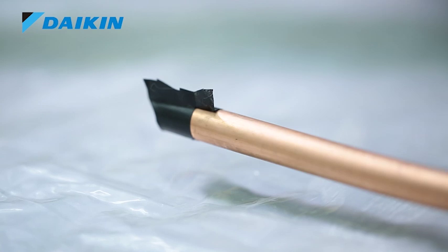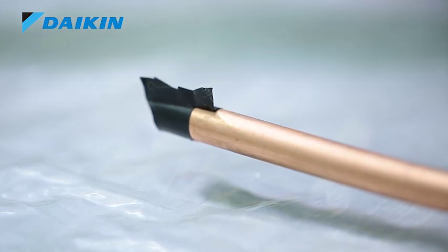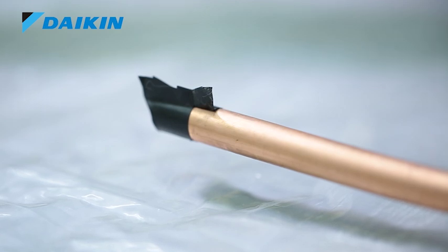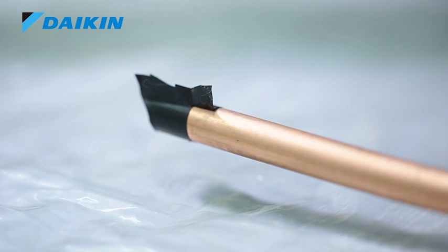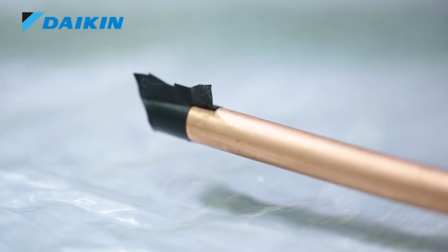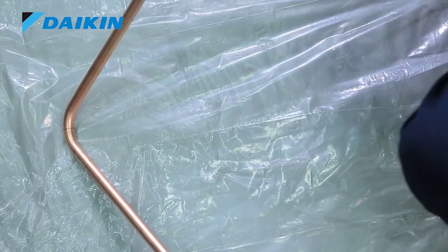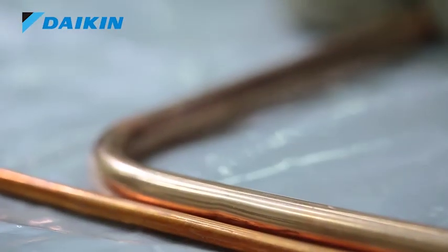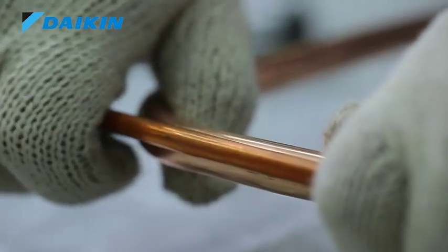After cutting the required length of copper pipe, put a seal on the remaining part of the copper pipe so that contamination cannot enter and it can be used further for any installation. Next, bend the refrigerant pipe as per the layout. Try to keep the minimum number of bends in the piping to minimize the resistance to gas flow.